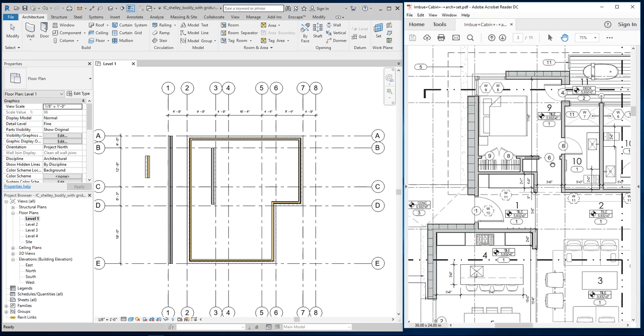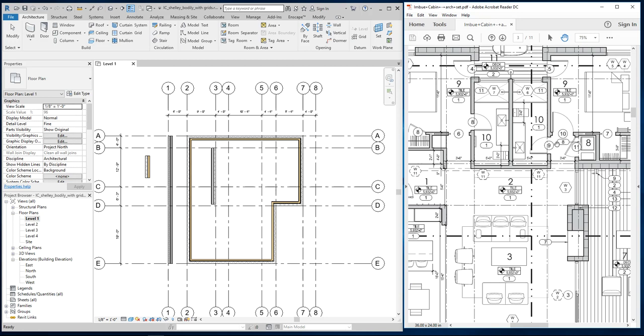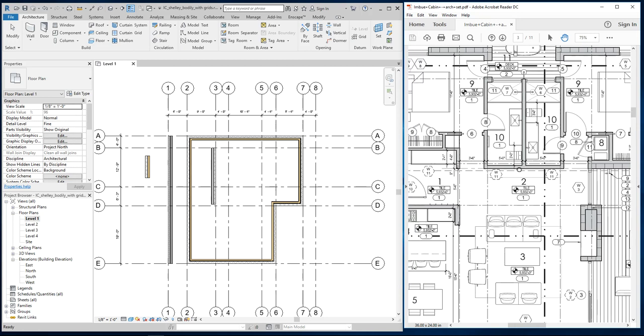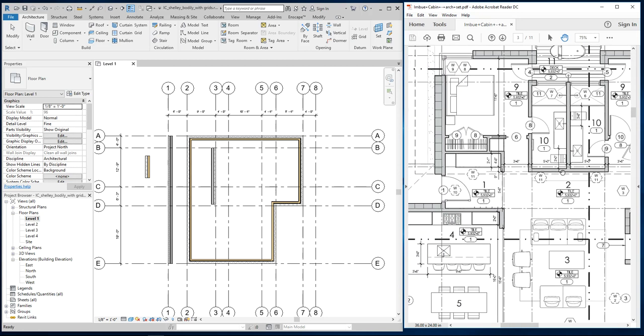Go back to our floor plan here. Okay. And I can look and find all the sizes of all the doors needed, right, on that same sheet, essentially. But let's talk about how we're going to add some doors here to our floor plan. The door command is located here. It's DR for a shortcut. And the window command is located right next to it.